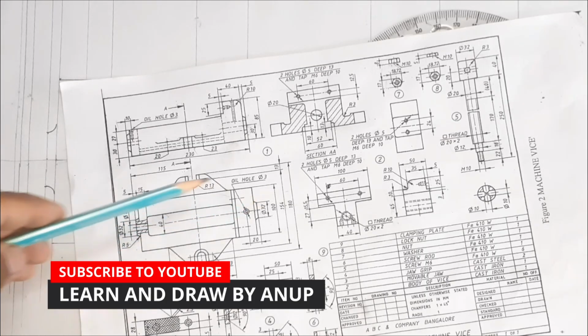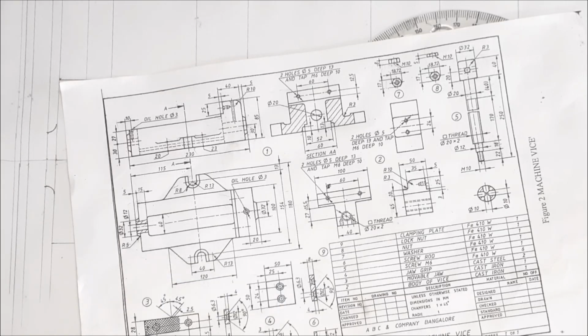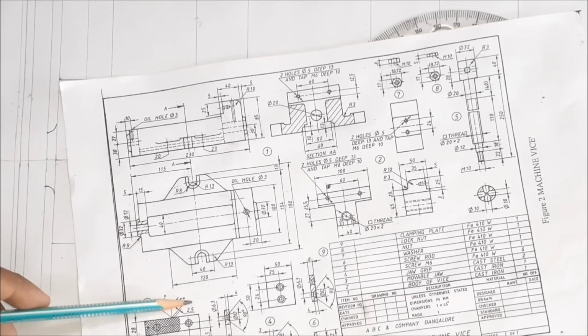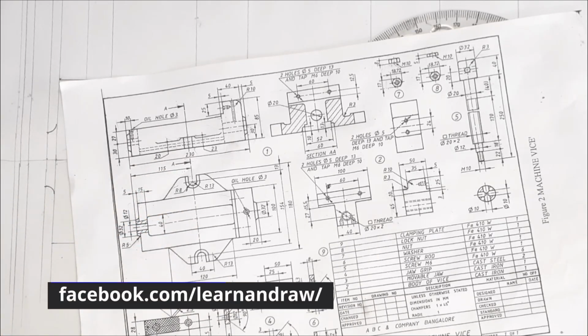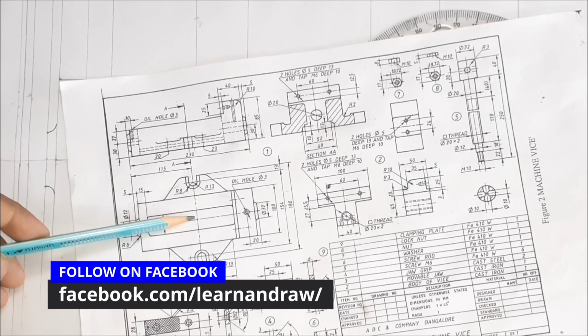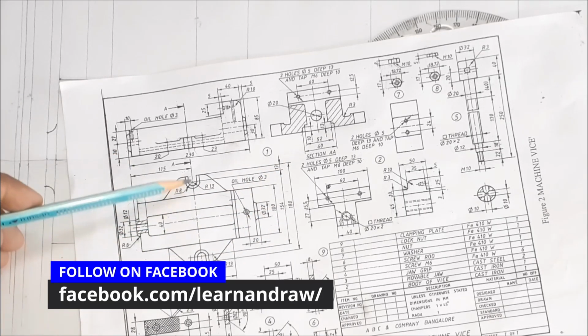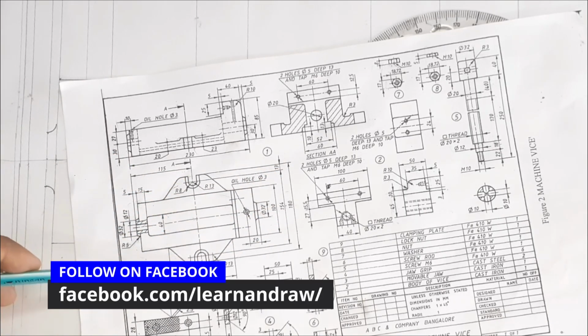To draw this one, first let us mark these points on the axis line. You can see here this is the axis line. Since they are in the middle, we have to mark these points on the axis line. The total length is 180, so from the axis line we have to mark 90 mm and 90 mm.